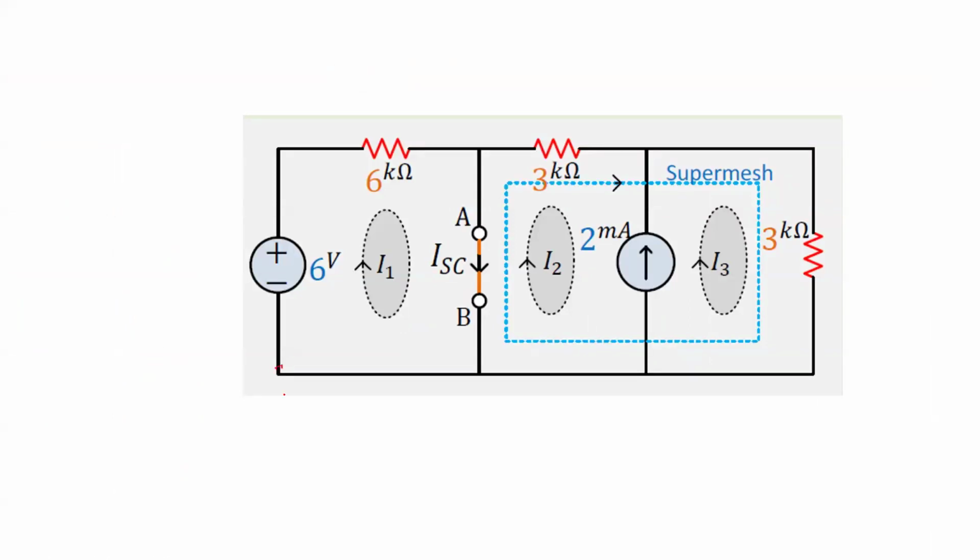So look here, guys. What is the current here? The current here is 0. So what is the voltage here? It is 6 volts. Very easy. This is a short circuit, so the voltage here is 0 volts. Okay, that's easy. So what is the current here? Ohm's law, 6 minus 0 divided by 6, which is 1 ampere. So now, that's what I need.